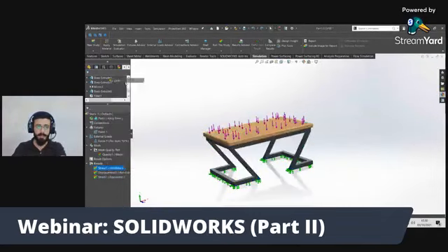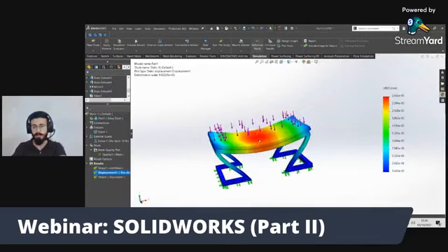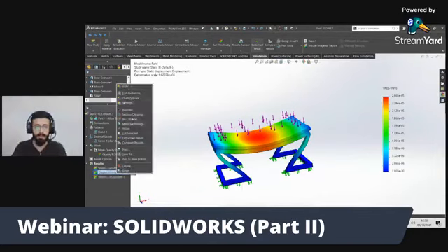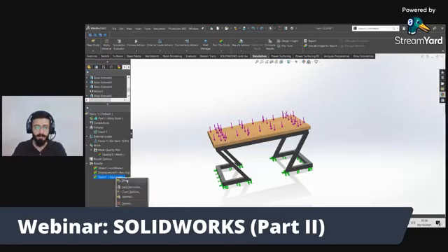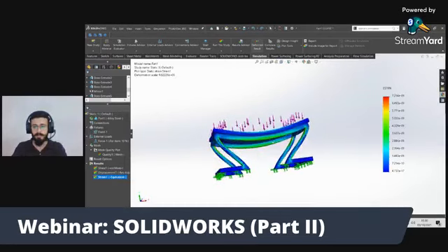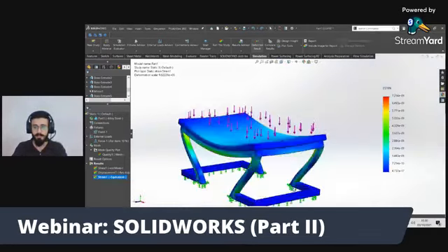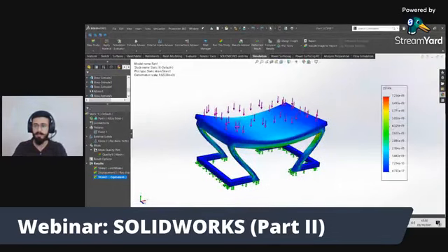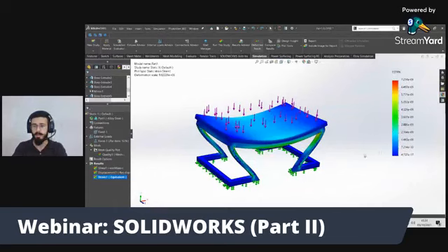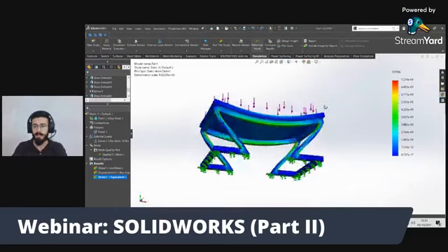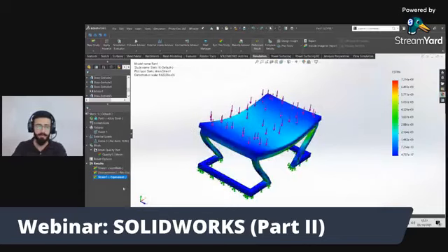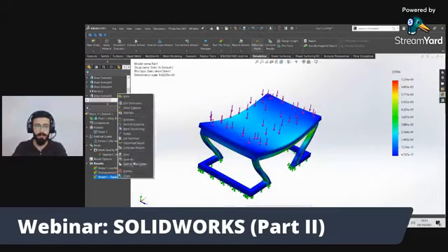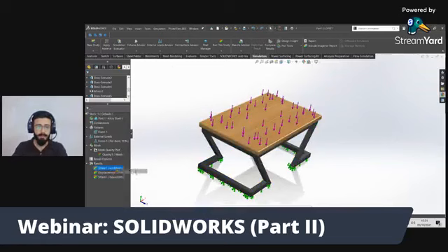Now we will hide the stress. What will be the displacement here? This is the displacement. This area, the central area, is the weakest. And now we will see the strain. This is the strain here. See, stress and strain are almost the same in this object. This is the plot which shows color-by-color mapping, which area is more affected, which area is least affected, which is most affected.